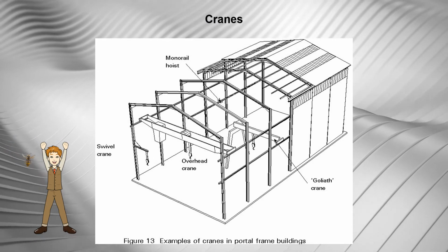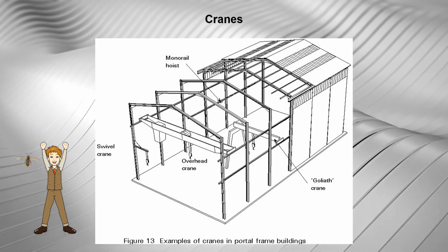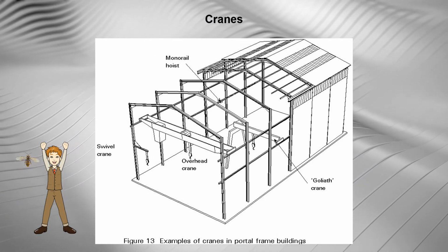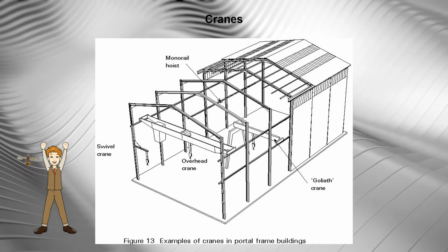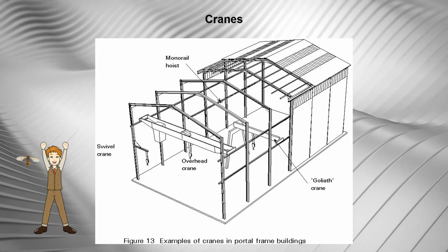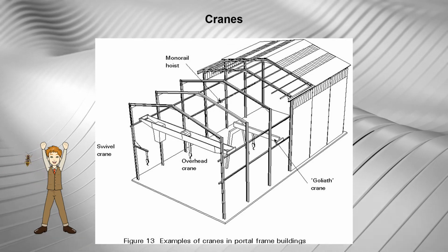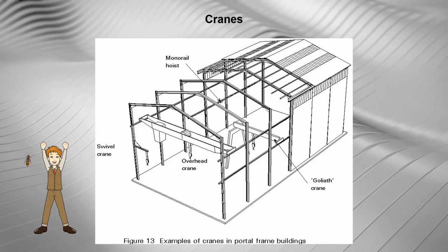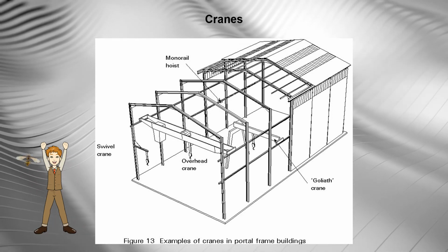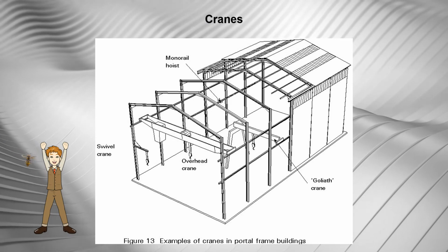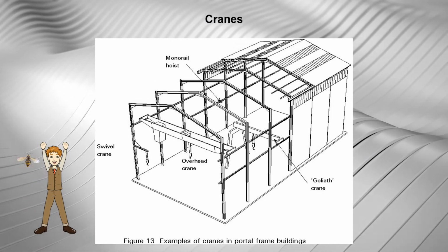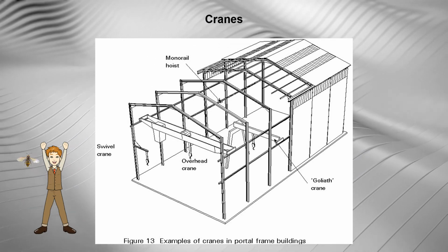The enhancement factors to be used depend on the particular plant and its acceleration and braking capacity. Manufacturers must be consulted where heavy, high-speed or multiple cranes are being used. To take into account dynamic effects due to cranes, the maximum vertical loads and the horizontal forces are increased.